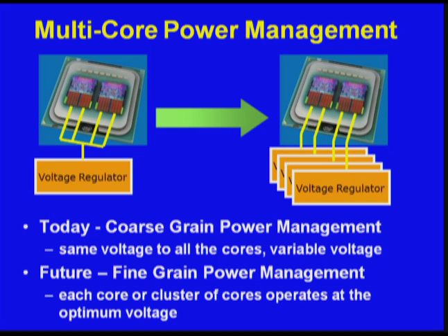So what that means is that you have a lot of wiring to deal with, a lot of residual inductance and capacitance to worry about that you have to contend with to switch that voltage on and off, or lower it, which means that there are long delays involved. Of course, as we all know, microprocessors and GPUs all like to switch very fast. Workloads change very fast. So there's not a very good match between how fast you can change the voltage versus how fast the workloads change.